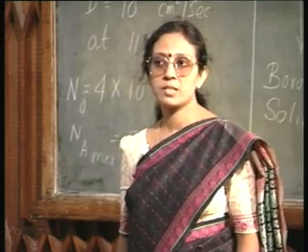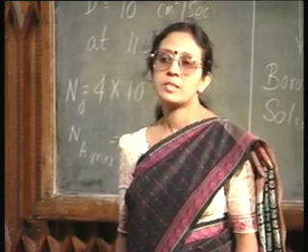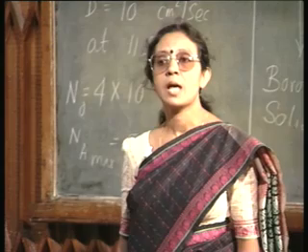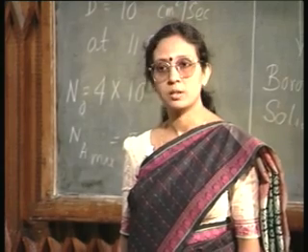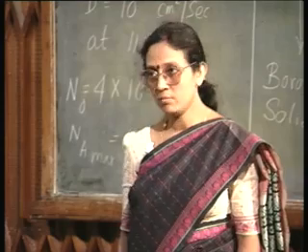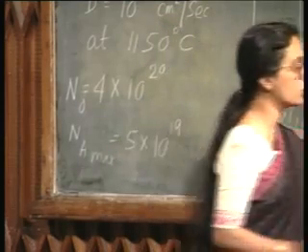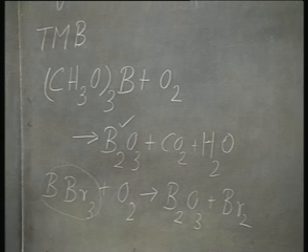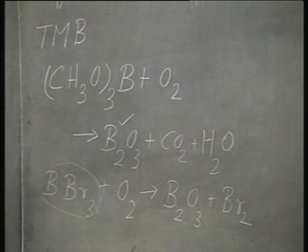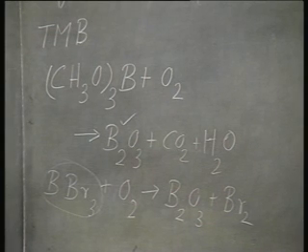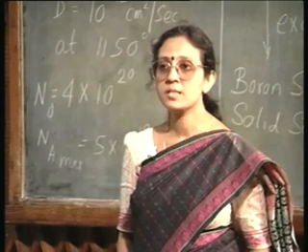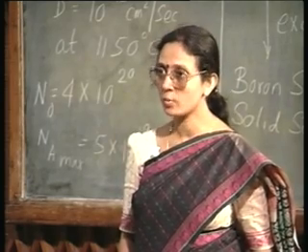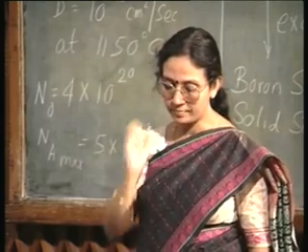The second disadvantage is, if these halogens, chlorine, bromine, etc. are present in excess, it will cause halogen pitting of the semiconductor surface. So, excess bromine pitting might occur. So, you have to control the amount of this boron tribromide. But there is an advantage also. In small quantities halogens will act as gettering agents. You have seen this for chlorine. Similarly, bromine can also be used for gettering.